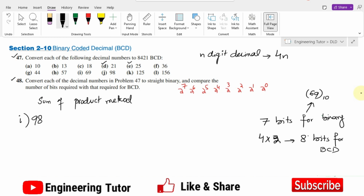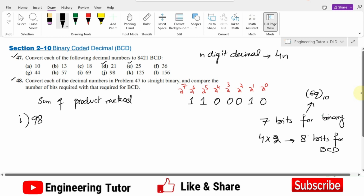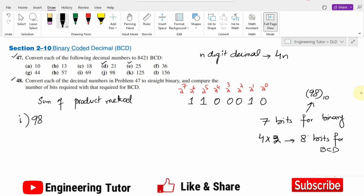So this 2 to the power 7 is 128, this is 64, so 64 here, 64 plus 32 is 96. Okay, that is now 96, and 96 plus 2 is 98. Okay, so how many bits are required? So again 7 bits are required for the 98 as well. Okay, because 1 2 3 4 5 6 7 bits are required for the 98, while the same 8 bits are required for the BCD.